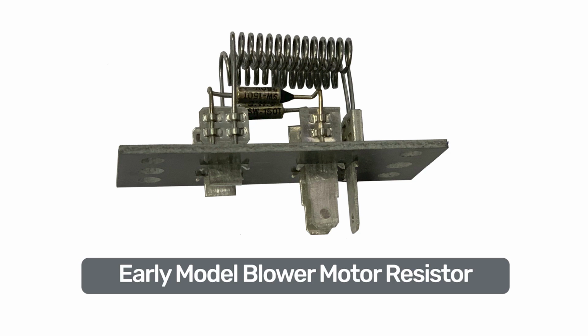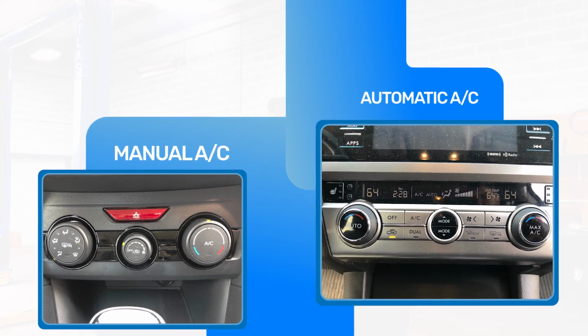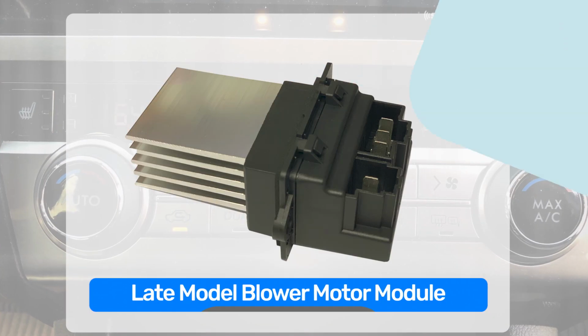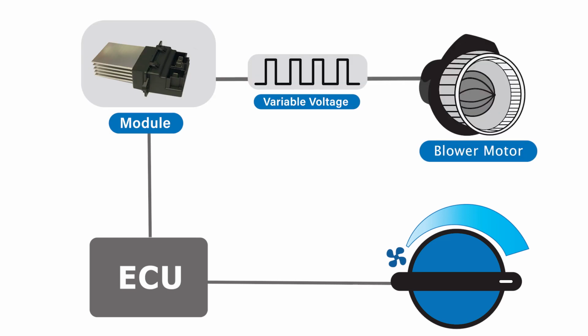Now so far all of these have been resistors, and these are usually for your manual AC. Now a blower module is usually for your automatic air. And usually it's a smooth turn. It's not a 1, 2, 3. As you send a signal to your computer, just letting it know that you want to increase or decrease your fan speed, the computer actually sends the information to this module to control the speed. If this goes out, most of the time you lose blower speed altogether.